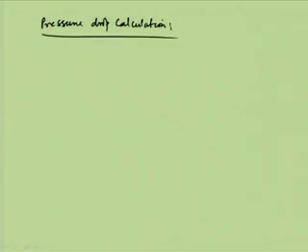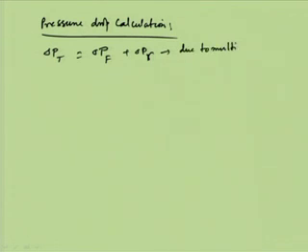We have to look at both shell side and tube side pressure drop calculations. In the case of the tube side, the pressure drop is calculated like this. Delta P total is delta P frictional loss plus delta P return loss. Return loss is due to the multi-pass heat exchanger and the return of the fluids, which we already discussed in the last lecture.